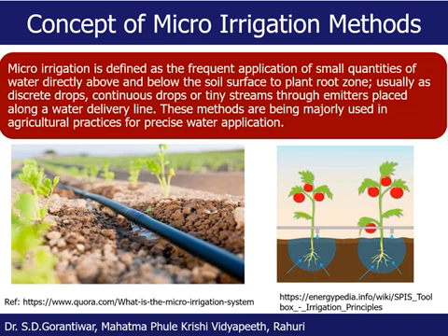So in case of the surface irrigation method, the variation in the moisture content in the root zone is from saturation up to near the wilting point. And in this process, the plant is subjected to water stress either because of the higher moisture content level or the lower moisture content level. Therefore, in case of the surface irrigation method, it is not possible for us to maintain the desired level of moisture content in the soil in order to have proper growth of the plant.